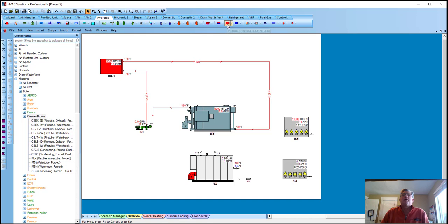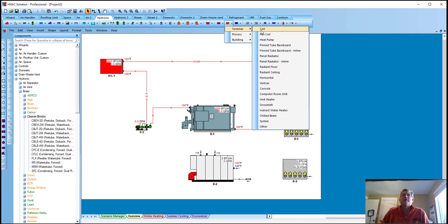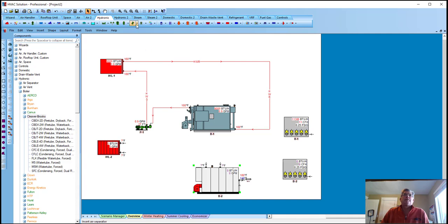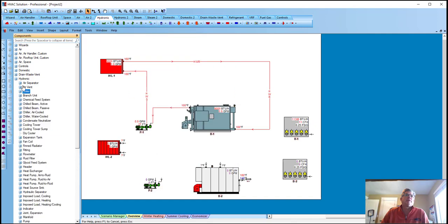And then I'll come up here. You'll see up here on the top, so I can get components on the left-hand side or the top. There's a coil. You can just grab that and move that. A pump is here at the top. I'm used to using this top toolbar, so I like kind of going to that. All these things would have been found on the side here. If I would have gone down alphabetically to pump, right down there, you'll see the pump. Or you can type in and search for the components right there, making that real easy.